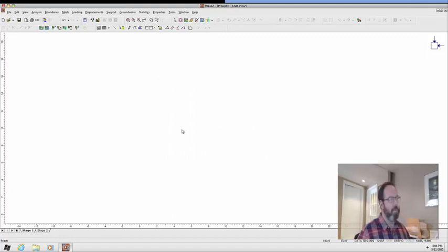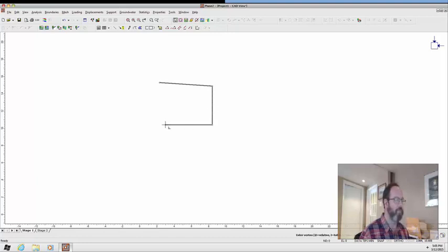Okay, so the first step is to build your model geometry, and you have to include all the geometry that you're going to include, the interior and exterior. So I'm going to make the interior tunnel boundary for starters. So I go up to add an excavation. And then you can see down in the bottom right, there's an area where you can enter information. So you can either click a bunch of vertexes for an excavation. I'm going to hit Control Z to undo that. Or you can enter them down below if you want to put more explicit locations.